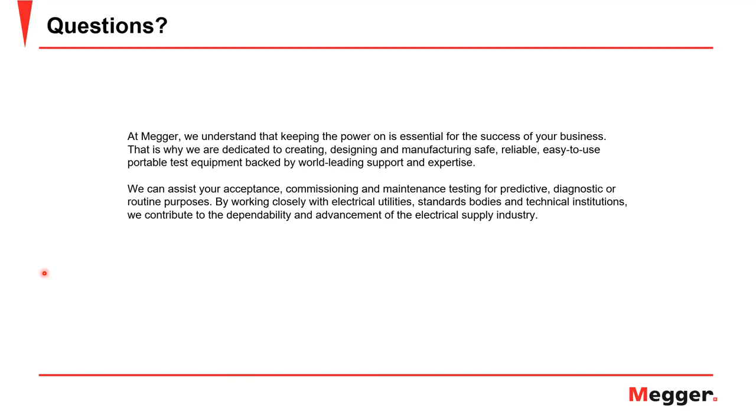In some systems, it makes sense to do only three-phase reclosing if the system is too highly loaded, for instance. If the system is too close to its nominal load, when you do single-phase reclosing, you are overloading the other two phases, and you could create problems with breakers upline, which could see an increase in the amount of ground current and things like that.